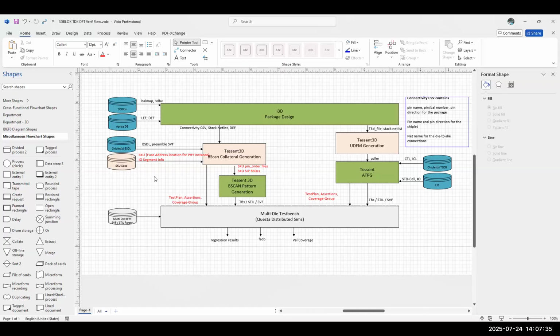Right. And then there is another read address, where after blowing, they come back and read that particular fuse value and see whether the fuse is already blown or not. Those are two different address locations. For our boundary scan purpose, we are primarily interested in the second address scheme, the read address location. We want to ensure that if it is already enabled, that PHY is existing, then we can run this particular pattern for that PHY.